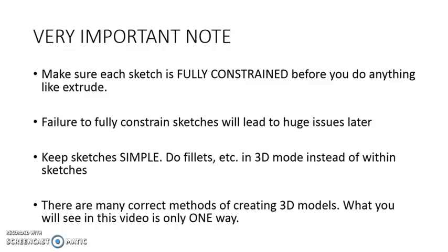Very important to note as we move forward, make sure that each sketch that you create is fully constrained. There's only one in this case, but if it's not fully constrained, that will cause issues later on with things like the revolve feature. So make sure that's just an important note to keep in mind for every single thing that you draw on Autodesk Inventor. Sketches need to be fully constrained.